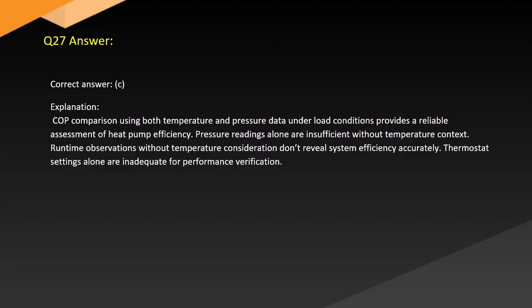Answer. Correct answer: C. Explanation. COP comparison using both temperature and pressure data under load conditions provides a reliable assessment of heat pump efficiency. Pressure readings alone are insufficient without temperature context. Runtime observations without temperature consideration don't reveal system efficiency accurately. Thermostat settings alone are inadequate for performance verification.